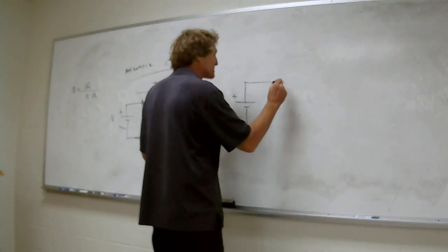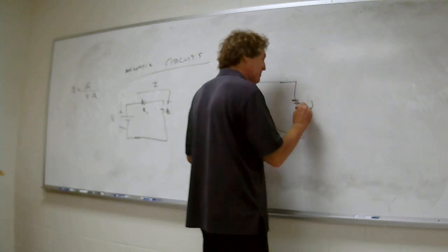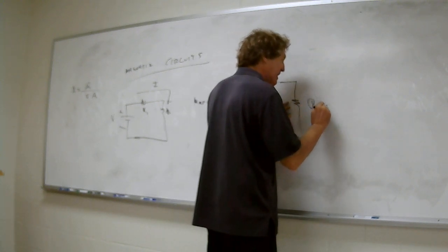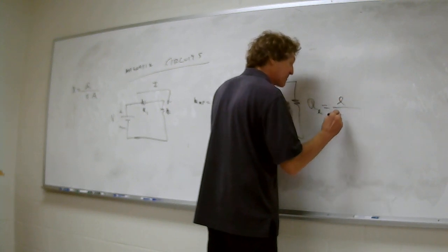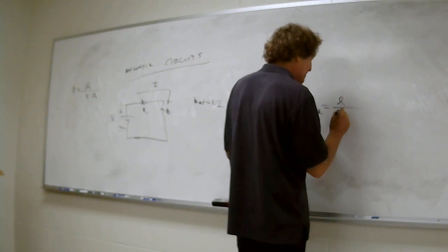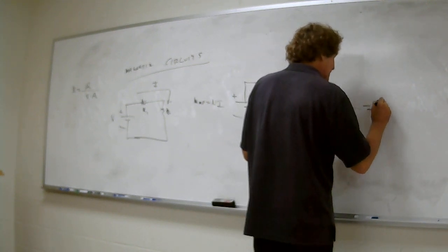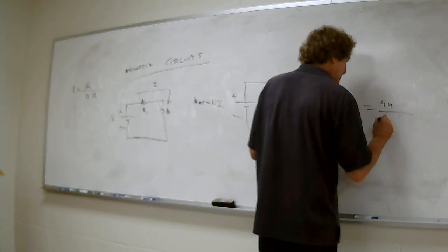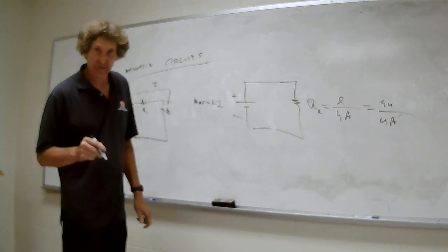Well, now you get something that's called reluctance. And this is the magnetic reluctance. It's proportional to length. It's inversely proportional to mu, which is mu relative mu naught, and inversely proportional to cross-sectional area. For the one I drew there, it's going to be 4A, the length, over mu times cross-sectional area would be the reluctance, like resistance. Y'all follow me?